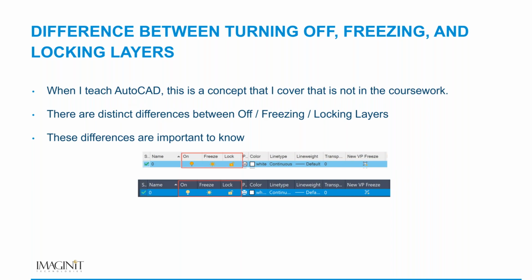Really, you should never use Defpoints. Just let it be what it is, create your own non-plot layer and use that instead. That's my recommendation. It helps prevent problems from occurring in your drawing, where audit sometimes may trigger a bad audit. Use your own layer and throw all that stuff there.